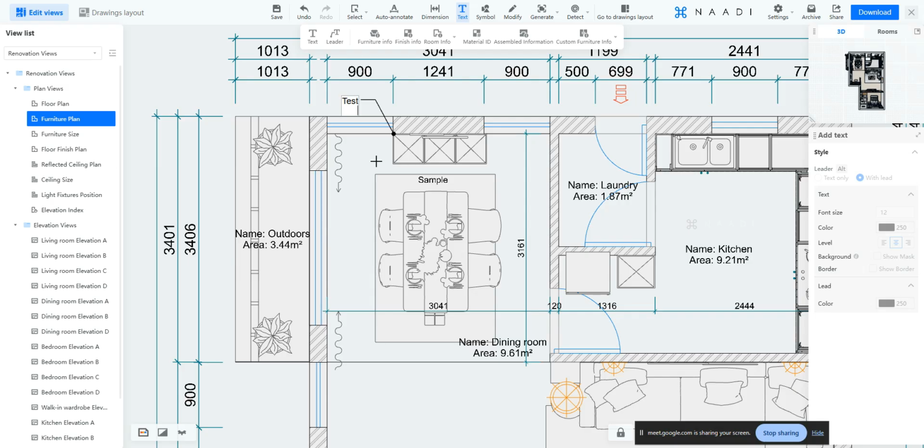Okay, so you can just press enter, you can just type it if you want more text information in a single point. So here I can just type all those things here. And you see, this is typically your M text. Any text here by default will be your M text. Okay, so you can just click it and add multiple text here. Can you see? A simple leader is added.